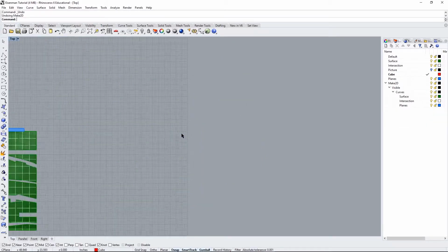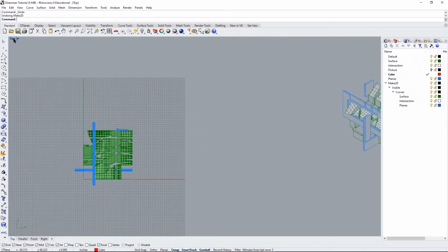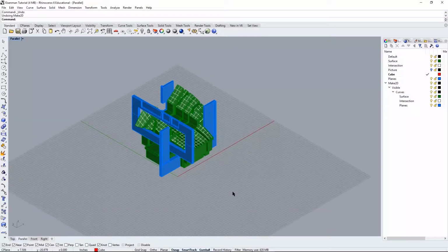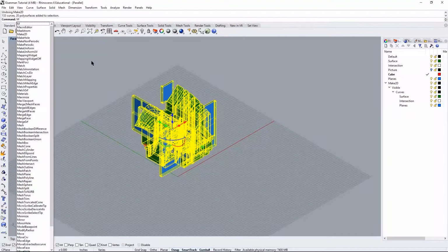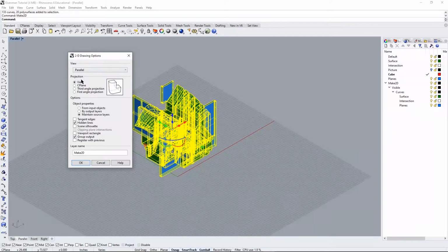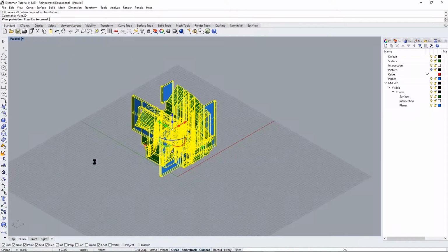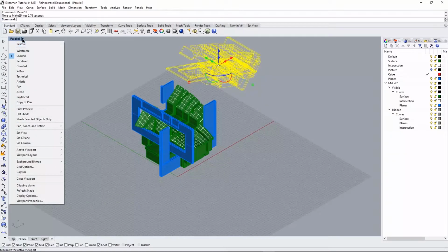You guys can mess around to see what hidden lines you might want to carry into the final drawing. I'm just going to go back and say I want the planes to only have hidden lines for my final drawing. So I'm going to go with that, do some hidden lines, make 2D on that entire thing.